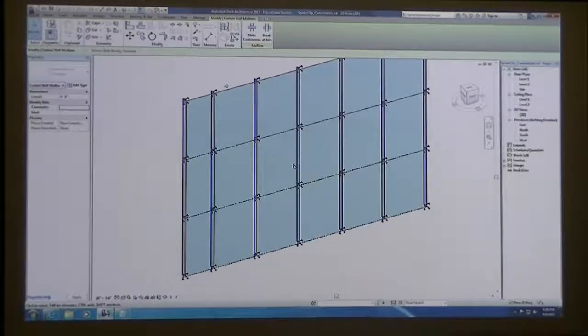And of course, I know you're going to have a lot of leftover space, because I also just realized that we did a 1.5 gross square footage to net square footage calculation, which is the maximum of inefficient floor plans that you could have. And I just realized that in this program there was a little bit of circulation space accounted for, but their ratio was more like 1.17. So they're planning on a very efficient hotel.